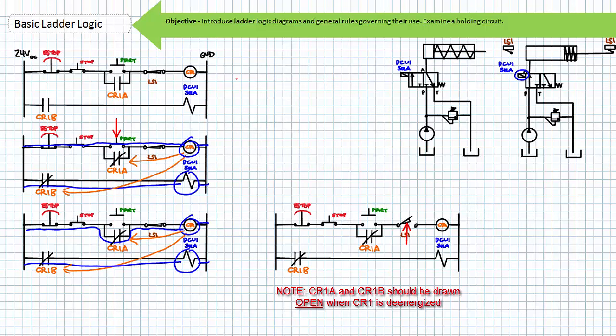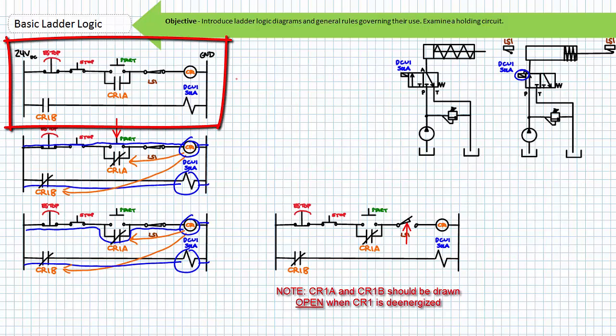Note, while the cylinder retracts, limit switch 1 returns to its normally closed state since it is no longer being actuated by the cylinder rod at the limits of travel. The system returns to its natural start state, ready to initiate another one-cycle reciprocation.